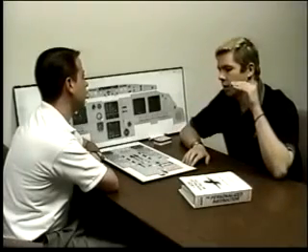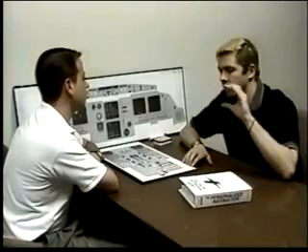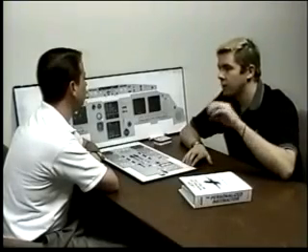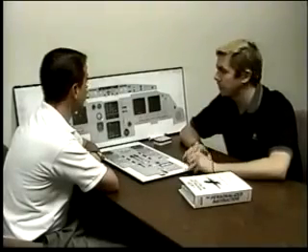If I were to go from 200 feet down to 15 feet, the localizer, if it's lost, or if I deviate by more than a quarter dot, it's going to illuminate the autoland light. And then from 200 feet down to 100 feet, the glide slope, a loss of or a deviation by 1 dot or more, is going to illuminate the autoland light.